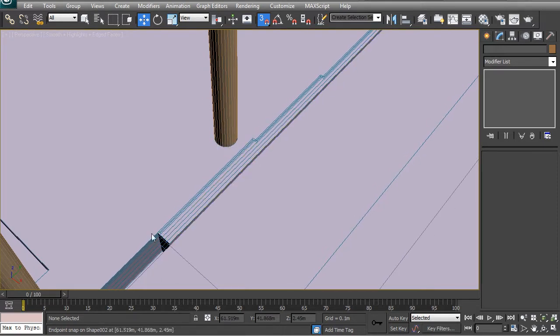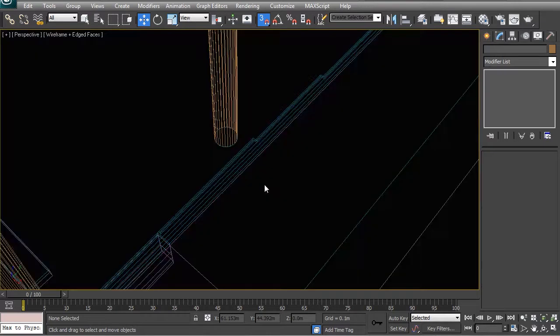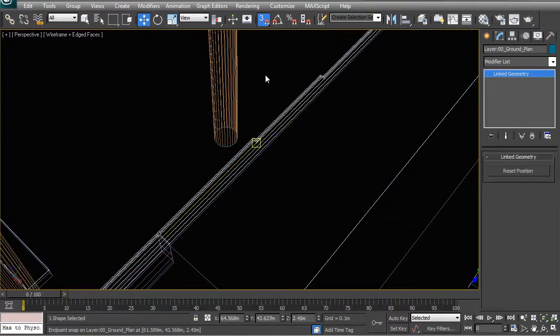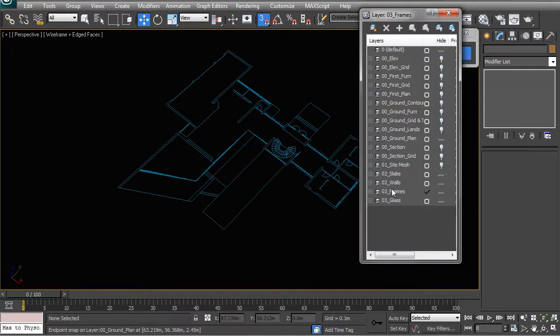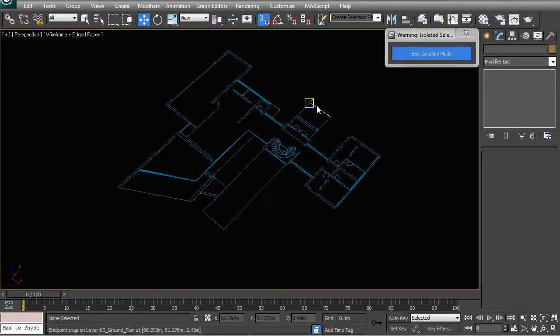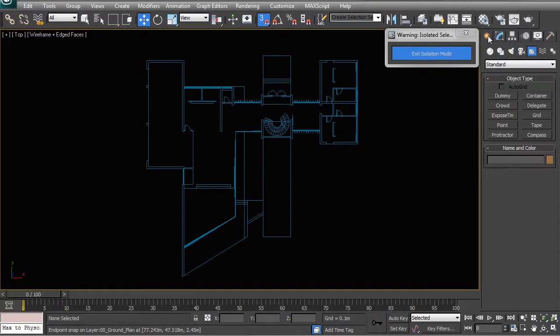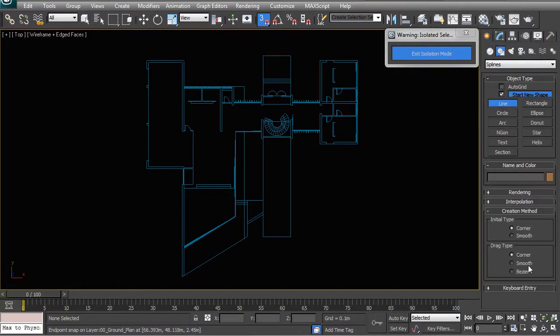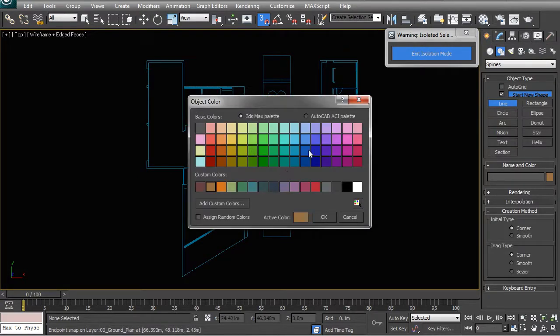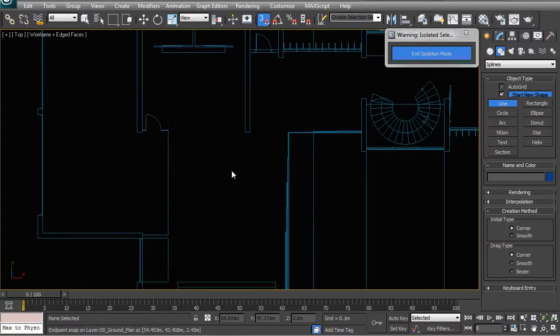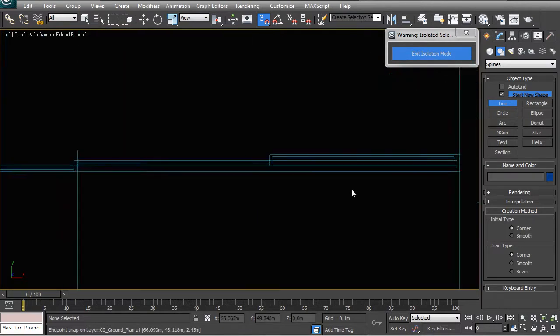What we're going to do though is outline the bottom of this entire frame system, and we're just going to show that as a very thin frame about 1 or 2 millimeters high, so that we can at least see that being different to the surface of the floor. So let's go ahead and start modeling all of that. I'm going to make sure that I'm on my frames layer, and in my plan view, I'm going to start outlining that frame. Over here, I'm going to choose that frame color, and I'm going to start by drawing that object.